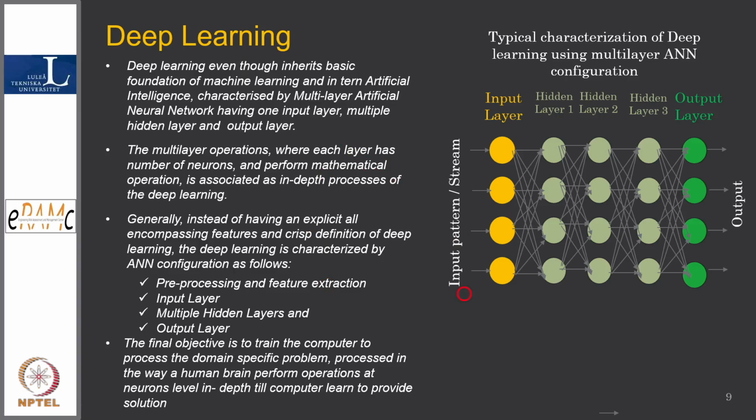That is, one is pre-processing of data. Process the data and remove noise, if suppose noise is coming with some signal, I have to remove it. Feature extraction: instead of putting the whole algorithm, or streaming the data, I can put mean value, standard deviation. Just for example, I am doing. There are many more things that have to be done, so that then it becomes more crisp, and it doesn't load the ANN, or the algorithm, and the results are much better. Okay.